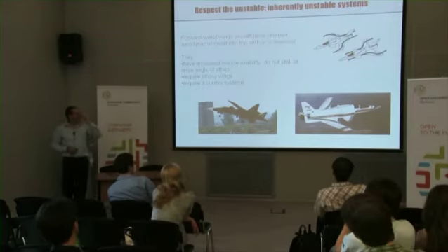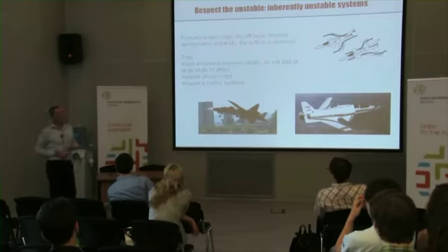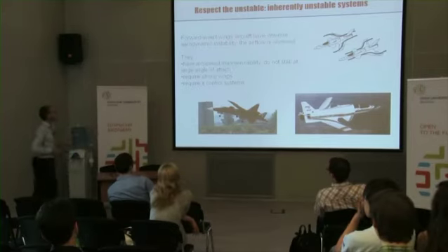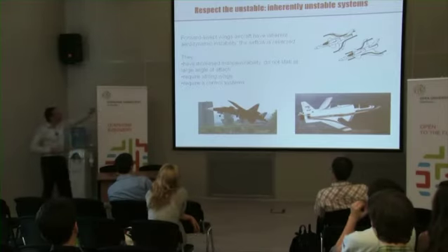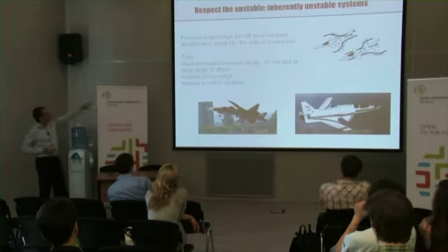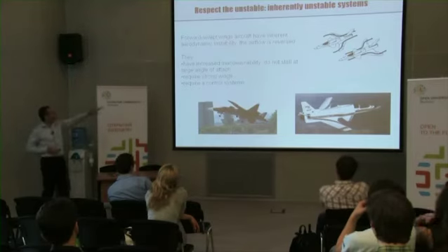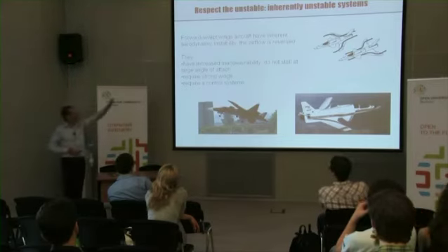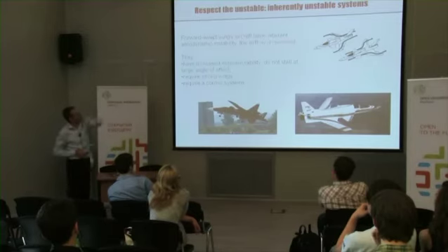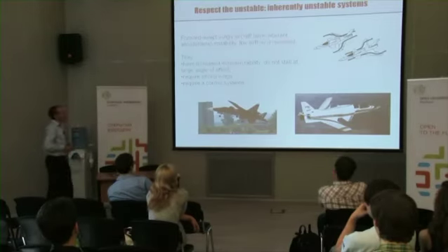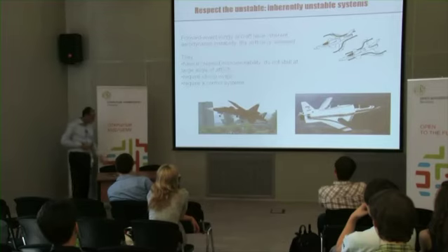What happens is that this aircraft actually is unstable. So if you let it go, it will crash. Okay, so you will need the control system. The reason why you would like to have this aircraft is typically these are military aircraft, because you have increased maneuverability. They do not stall at large angle of attack, which means you can go very high and you don't stall. But of course you require very strong wings, because they are somewhat suspended, and you require a very good control system.